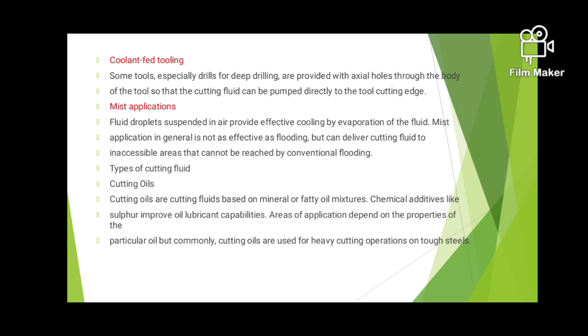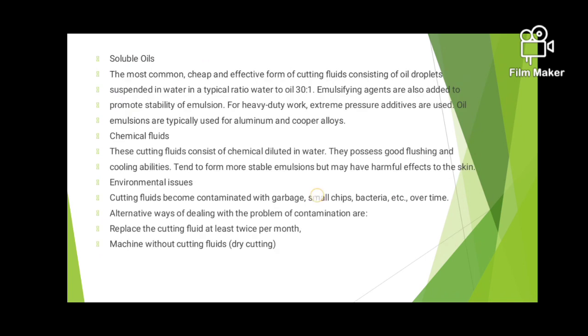Coolant feed tooling. Some tools, especially drills and deep drills, are provided with axial holes through the body of the tool so that the cutting fluid can be pumped directly to the tool cutting edge. Soluble oils: the most common and cheapest cutting fluids consist of oil droplets in water. The typical ratio of water to oil is 30:1.